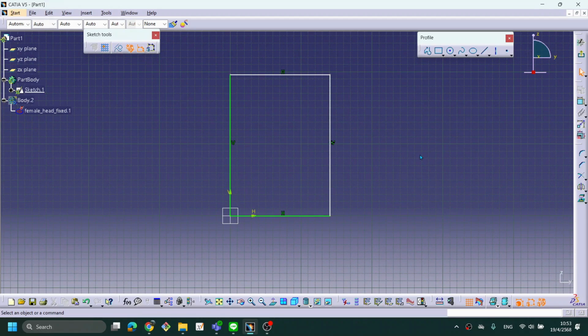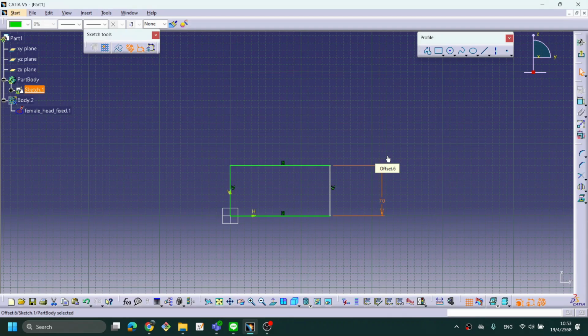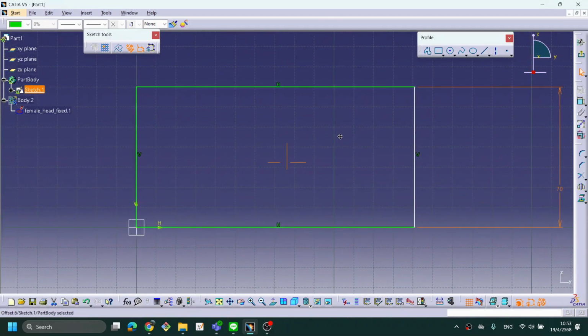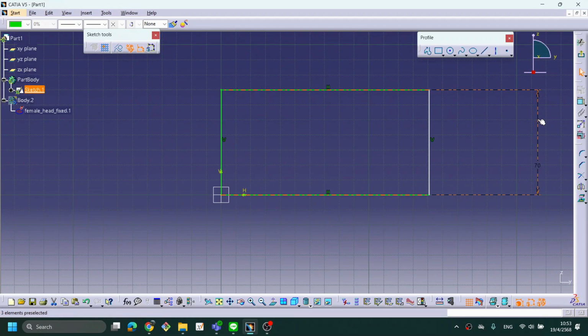Okay, I find the block, the raw material block, and I use the surface machining CAM module in CATIA to generate the two parts, right? Okay, inside of this block, right? Okay, and right now you define the size of this block, 70, right? It's very small, right? Because I will use just a mini CNC machine, right? That means it's very small. It's a mini CNC, small one, right?